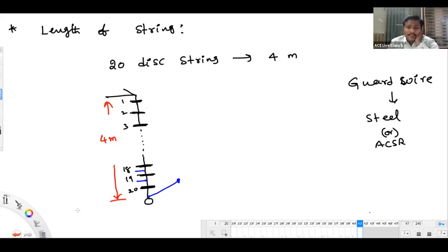Yes or no? Yes. Which are the major charging currents here? Bottom capacitance only, right? Bottom shunt capacitances themselves are the major charging currents. Those currents get cancelled by keeping even a short length of guard wire. Then there may not be a chance of getting 100% efficiency, but definitely there is a good improvement in the string efficiency expected, even though you are providing the guard wire only for some number of bottom metal links.